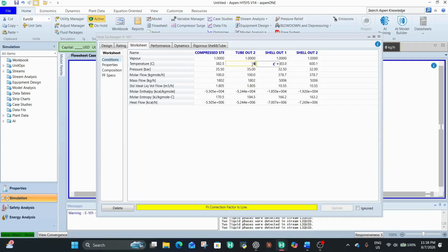Temperature cross. Let's walk backwards. 630. Doesn't work. 620. Doesn't work. 610. Does work without a temperature cross. Let's squeeze out as much energy as we can. 615. Does work. 618. Maybe not. 619. Doesn't work. So let's just stay at 618.